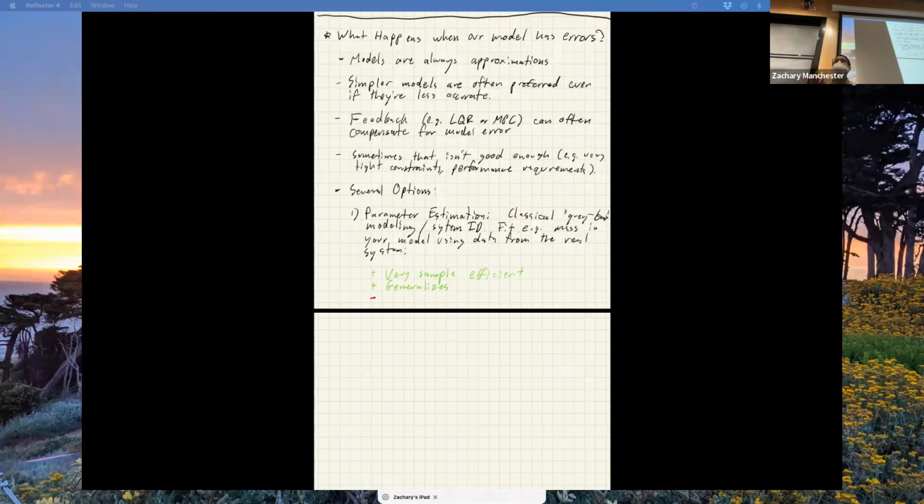But no matter what I do, I'm never going to capture the aerodynamic effects like lift and drag and weird propeller flapping stuff, all the weird aero effects. They're just not in that model at all. So there's no way I can possibly capture those no matter how hard I try with something like this. So there's inherent limitations to this approach. It assumes this model structure, and you're never going to be able to capture stuff that wasn't in that model to begin with.